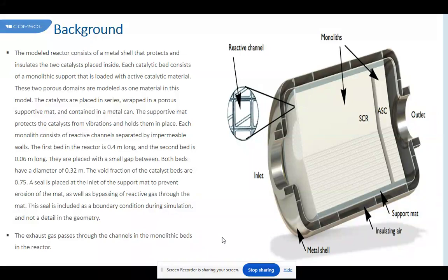In a separate study, Ramanathan and his colleagues in 2004 also presented simulations of the transient behavior and showed that for the case of back-end ignition, the cumulative emissions may be lower for metallic monoliths. However, for the case of front-end ignition, the light-off time is shorter for ceramic monoliths, leading to lower cumulative emissions compared to metallic monoliths.